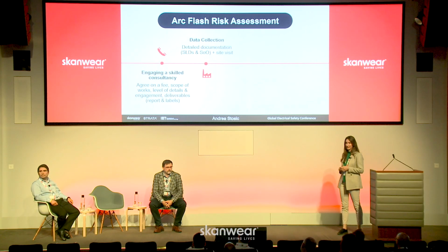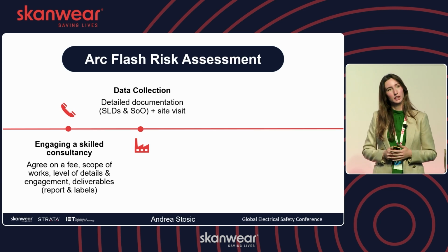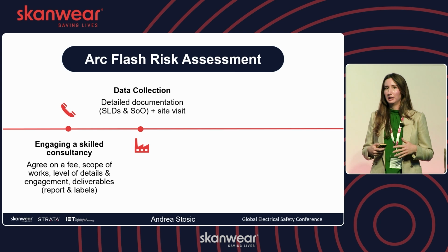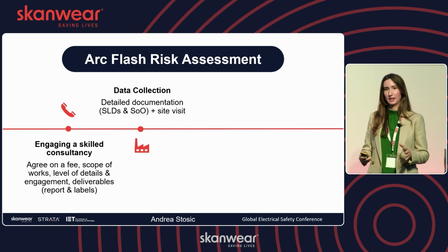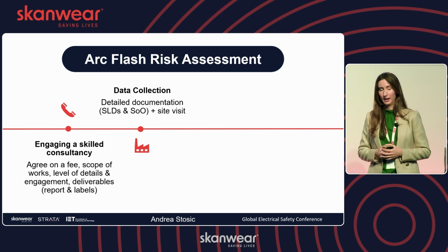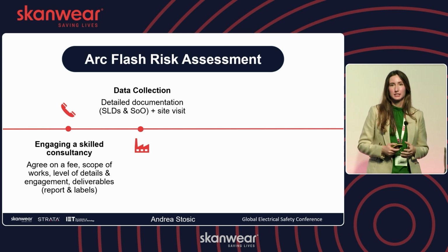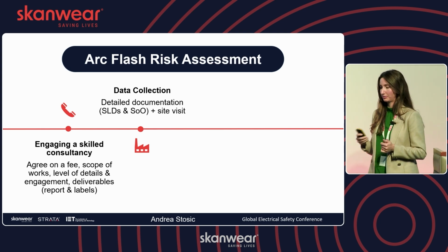Once you've done this step, the next step would be data collection or data acquisition. In my case, this step would be completely on me and my colleagues, to provide the consultants with the latest and greatest schematics, which of course need to be up to date, with the sequence of operations document, extremely important to provide that. Technical submittals, equipment data sheets. If it's an existing site, a site visit is necessary as well.